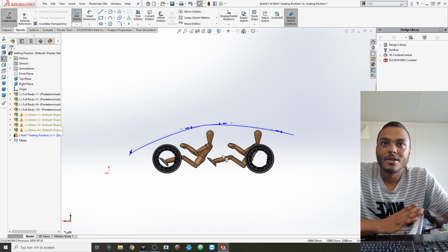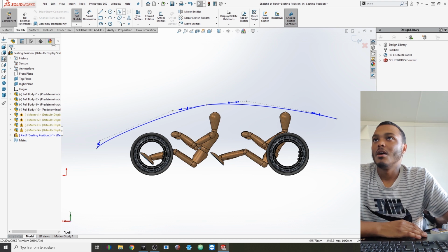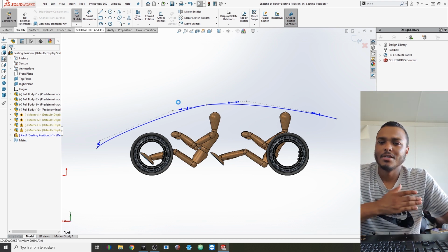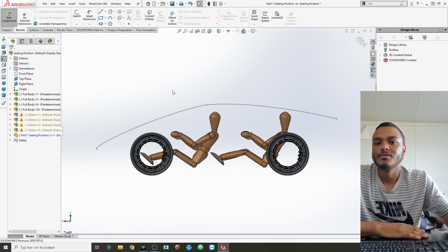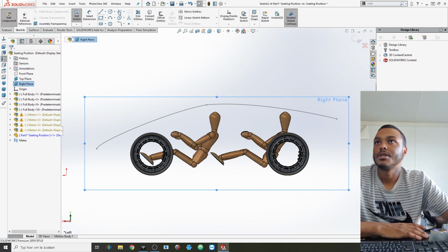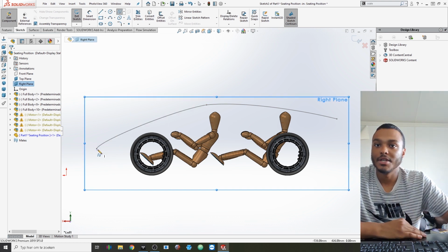Basically what we've got right now is the top line of the car, and now I'm going to make the underline. I'm going to do this in different sketches, because sometimes it's useful to keep those things separated, because you're also going to use multiple sketches to get everything rounded off. So again, I'm going to select the right plane, click on sketch, and use the spline tool. I also didn't mention that I don't use regular lines, but I use the spline tool most of the time when I'm dragging these lines across.